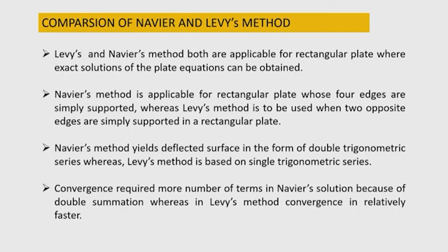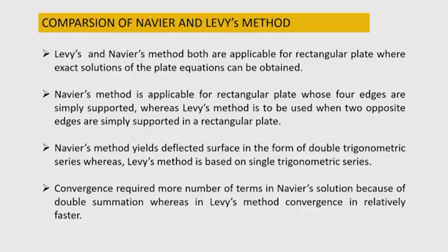Both Levy's and Navier's methods are applicable to rectangular plates. They have some general character: both use trigonometric series, and both yield the exact solution of the plate equations.